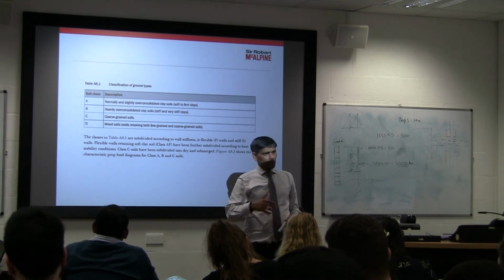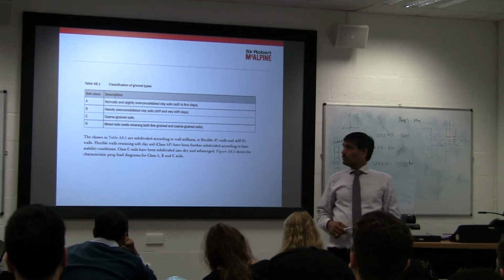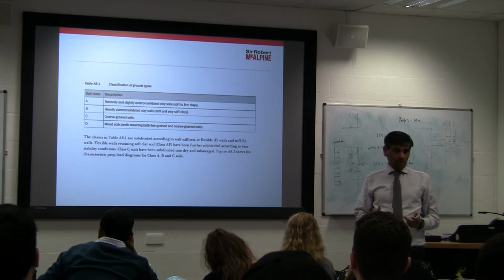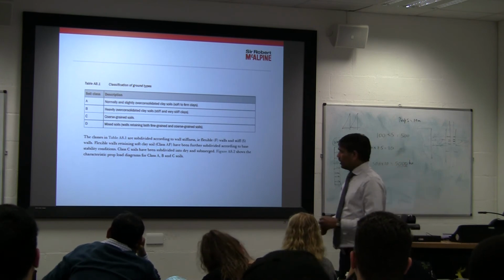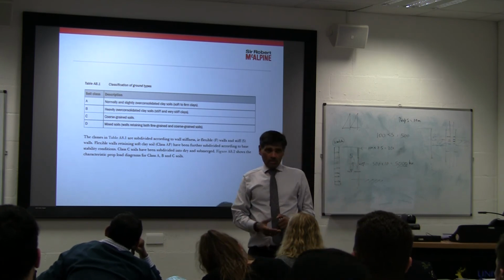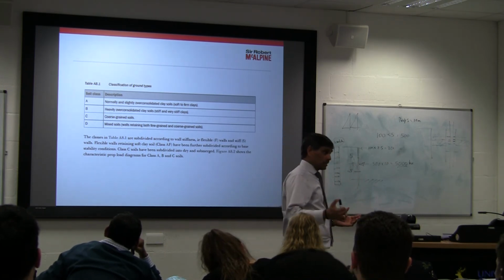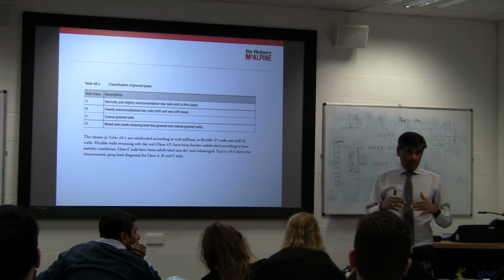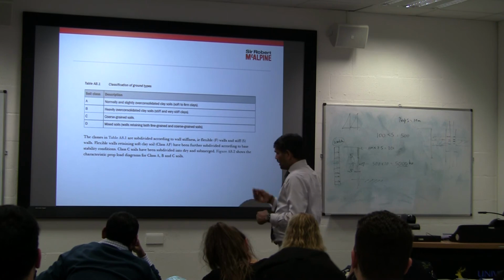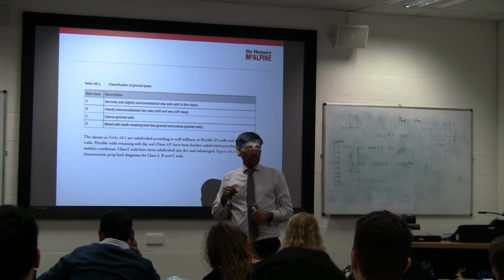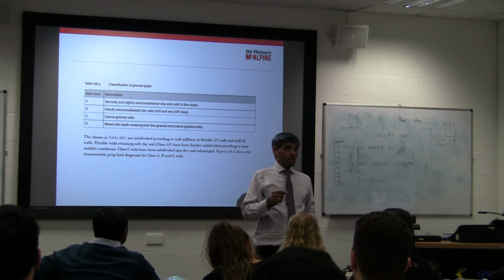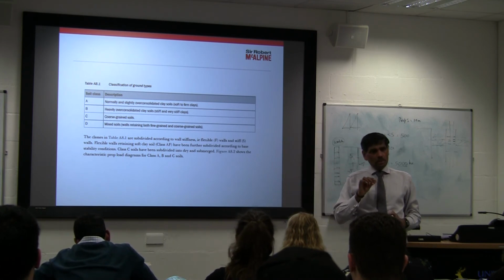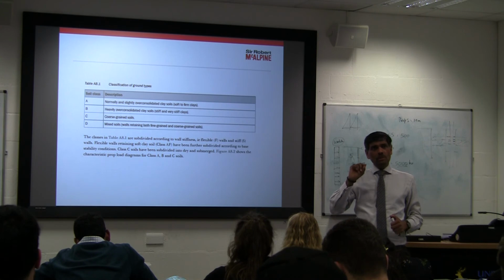Because most of the materials that we come across in London are very over-consolidated. That means there have been a lot of drift deposits in London. Some areas it could be 10 to 12 meters. So the London clay has already been subjected to very high pressures in the past. So you will see in Rankine's earth pressure, where you draw your active earth pressure and passive earth pressures using your phi values and so on, there is a plateau that is achieved in London clay.